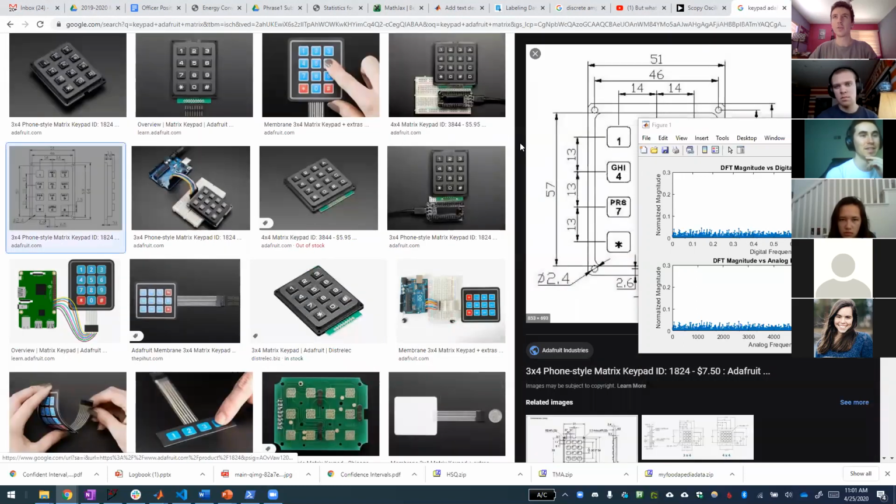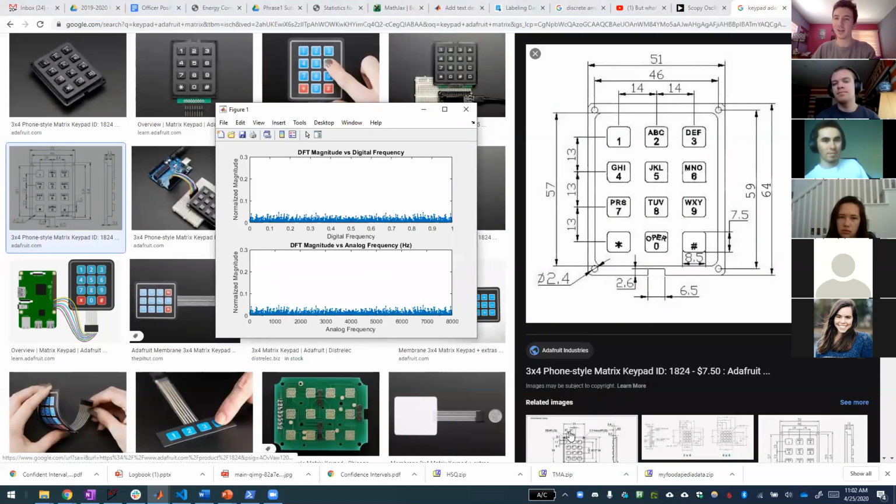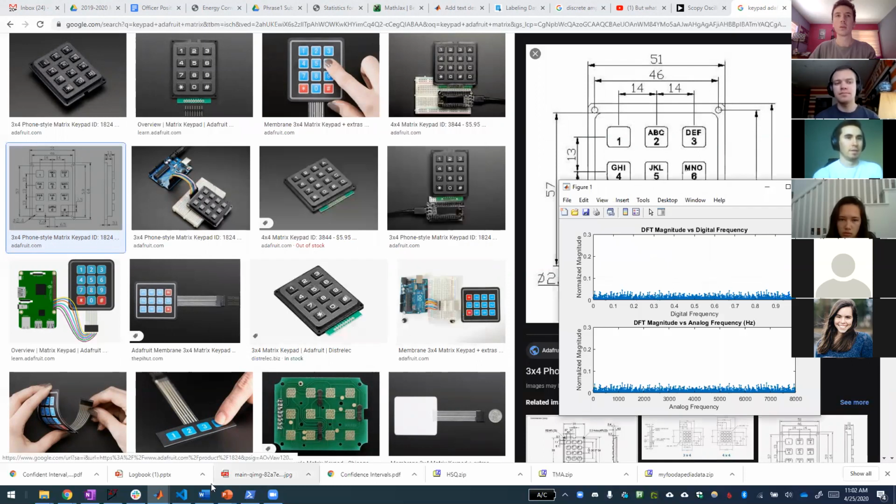They did it with a matrix to make the hardware easier, effectively. Each of these columns is wired to a specific voltage, and each of these rows is wired to a specific voltage. So if you press 9, you're going to get a specific column voltage and a specific row voltage. That's how they implemented it. It's easier to just play the two signals that correspond to whatever row and column voltage, as opposed to combining them and having the phone do all of that work to figure out what resulting frequency it should be. Gotcha. Yeah.